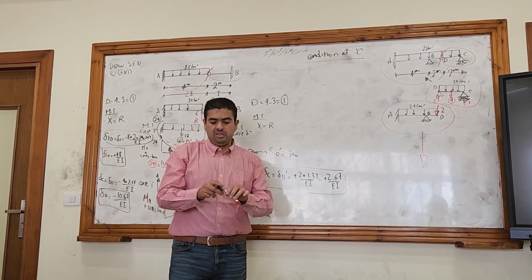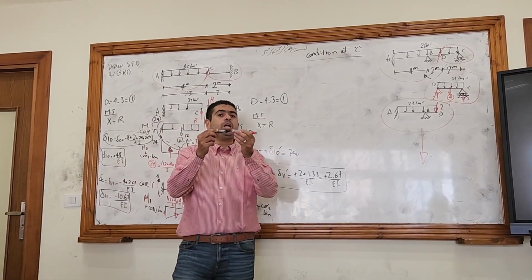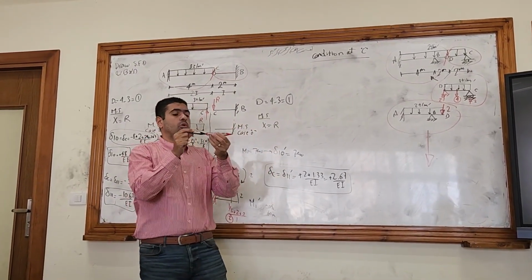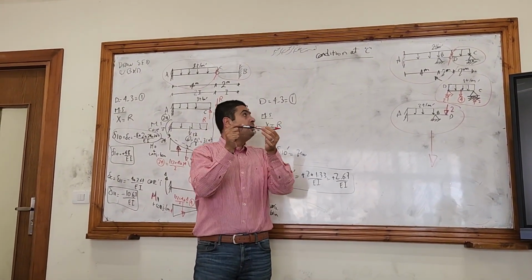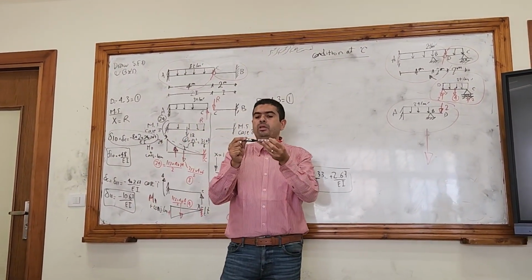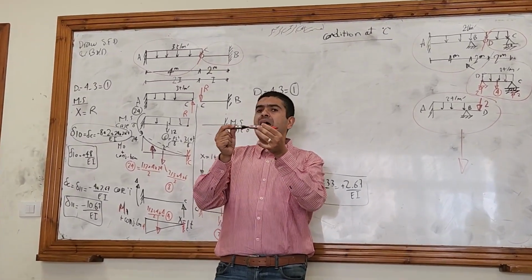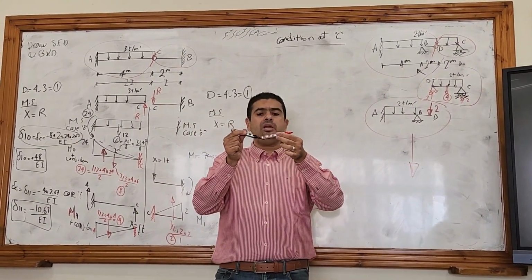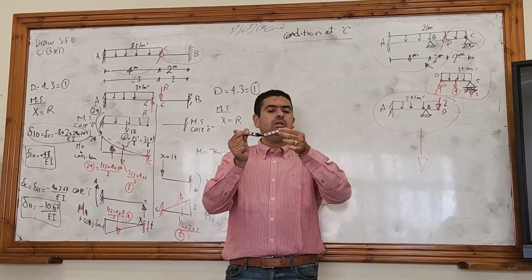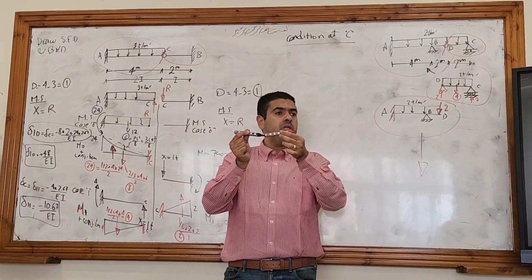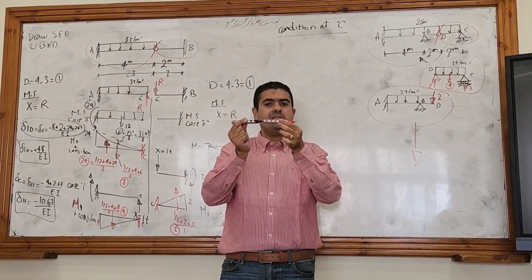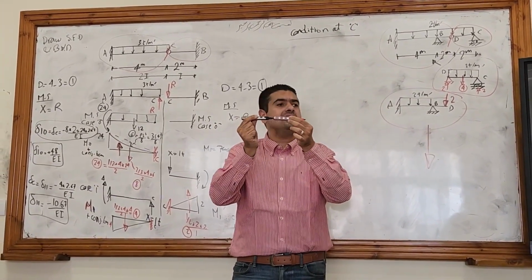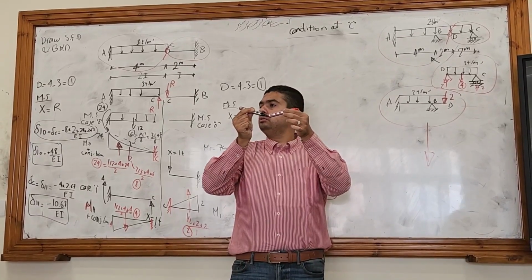Let's imagine this is our beam. The black part is called AC. The right part, the red pen, is BC, right? What will happen at the internal hinge C? It will move downwards like this, right? Nothing will stop it. So there is a vertical displacement at C. When you put a loading on this beam, the hinge at C will go down, right?